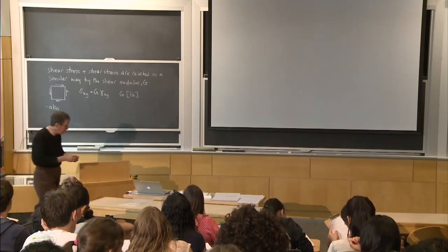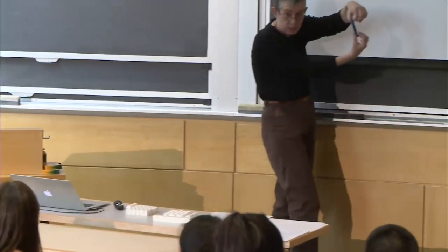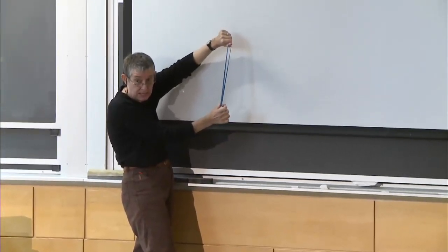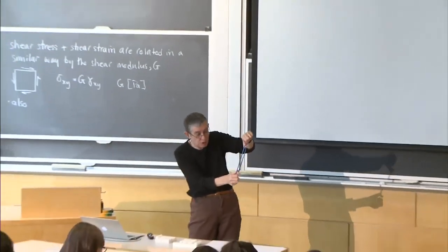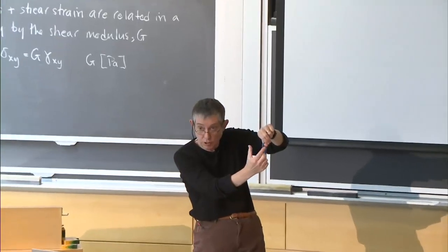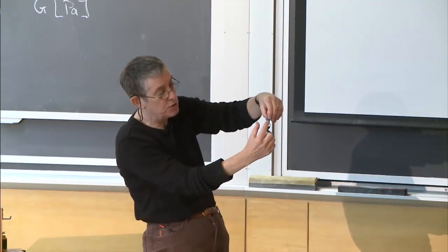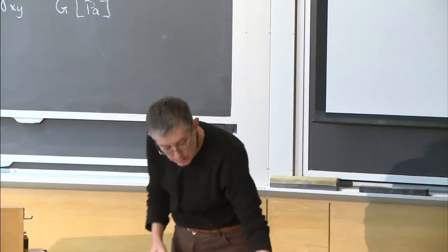Okay, so I brought a little rubber band with me here. And maybe if I stand in front of here, you can see. So the band is a certain width, right? And I'm sure you've all done this yourselves. If you pull on it like that, it gets skinnier, right? So you pull on it, and the width of it changes. Poisson's ratio relates how much strain there is in this direction and how much strain there is that way on, okay? So it's actually the ratio of the strain this way to the strain that way, okay?